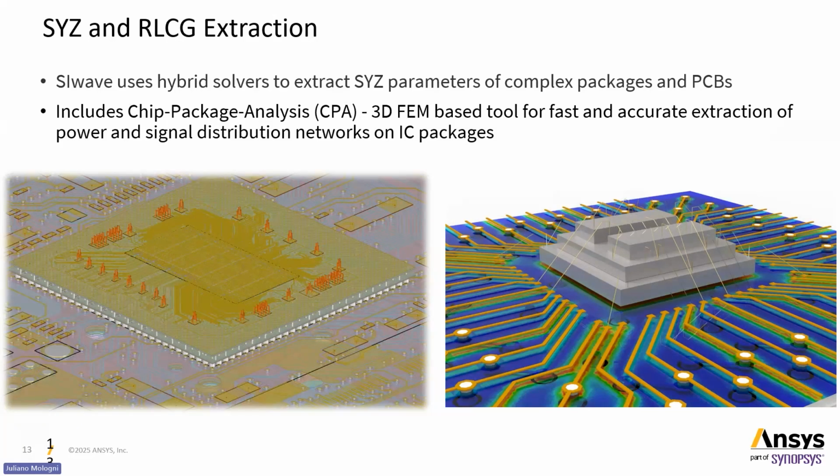Basically, you have a design, a printed circuit board, or in this case, a package on a PCB, and we extract either S parameters or RLCs, resistance, inductance, and capacitance, as a function of frequency, and we generate a circuit model. It could be a Touchstone file from S parameters or a SPICE model from RLC, and we take that model that includes all the electromagnetic behavior of your layout to run a signal integrity analysis, a power electronics analysis, or an EMI/EMC analysis.